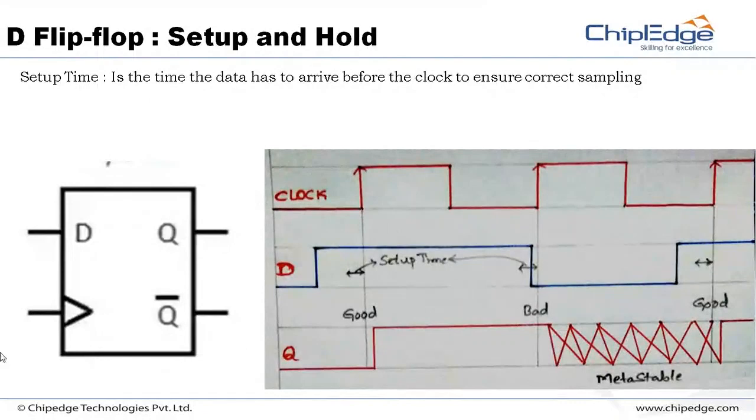See, this is my clock pin. The clock is coming at some period of time. Data has come and become 1. Now see, the clock edge is here and the data is well stable. It is 1, very well 1. So this 1 will be sampled and you get the output as 1.